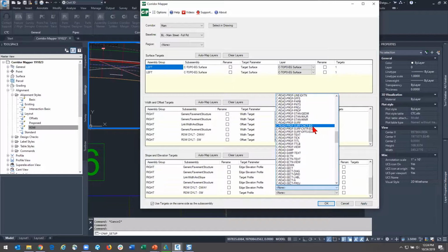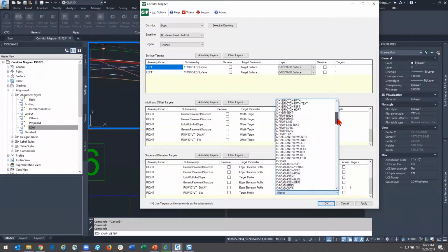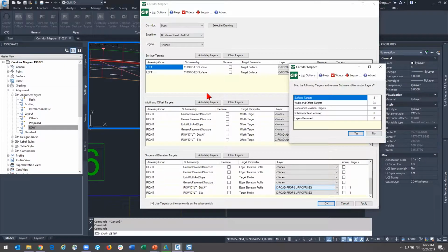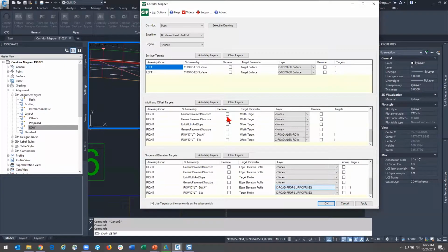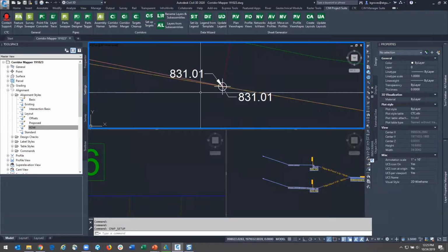Because I'm not changing the design of areas of land that I don't own. And I've got a surface layer specifically for my center line, my connected alignments, my center lines, or my offsets. In this case, my right-of-way is an offset type alignment, and that is the layer that I'm going to go with. And now when I run this one last time, I will see that those spot elevation labels are going to match, as they do right here.